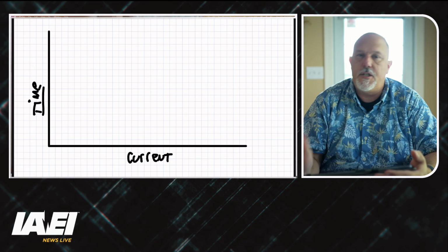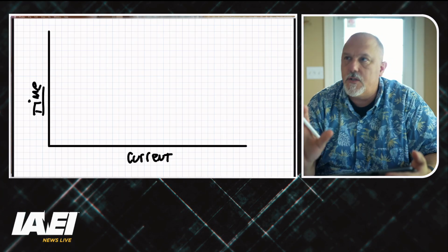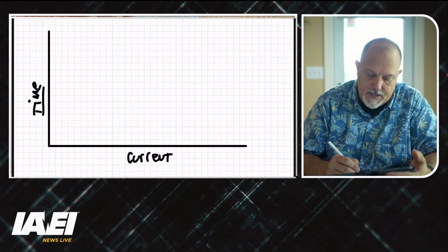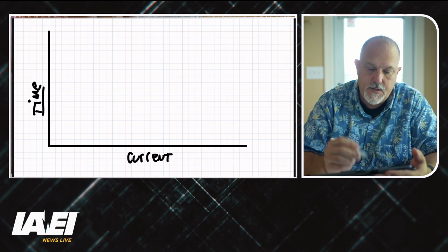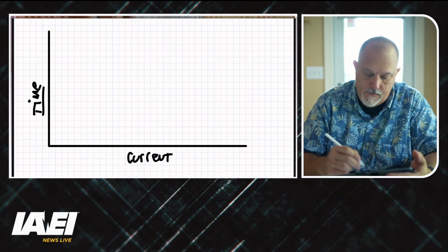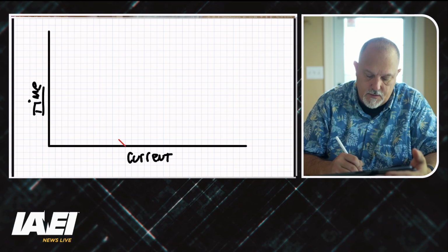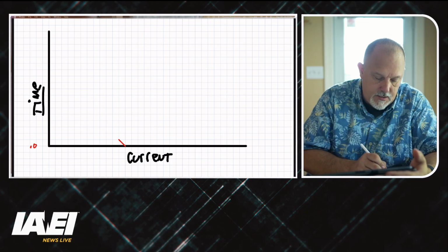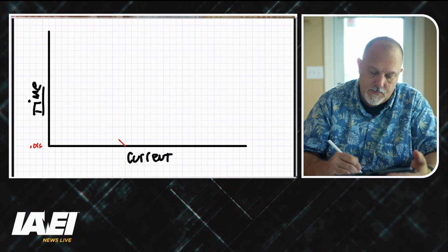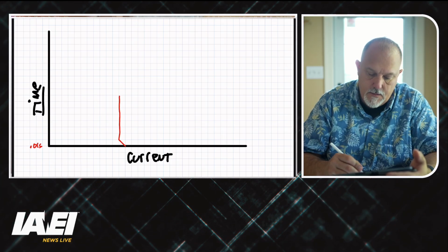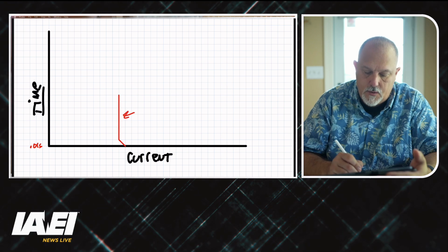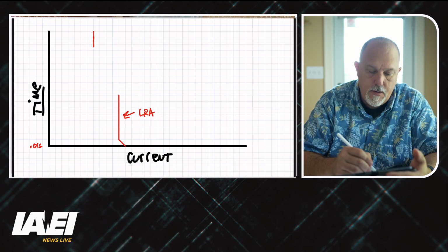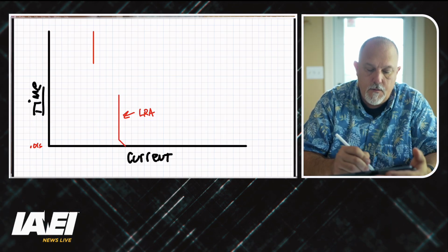So what she would do is, she says she focuses on the motor and the motor characteristics. So she's looking at the asymmetrical, which is, let's do this in red. The asymmetrical start curve would look something like that down at close to 0.01 seconds. So this is 0.01 seconds. Then you'd have that is your locked rotor amps. And then you'll know your full load amps.